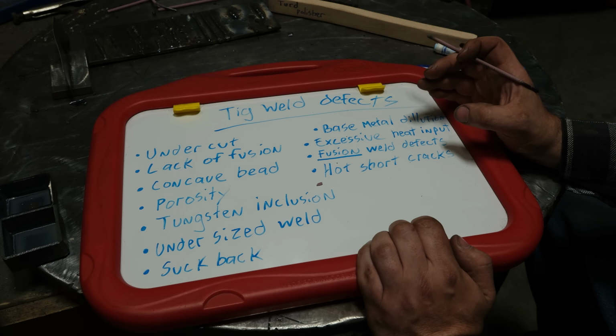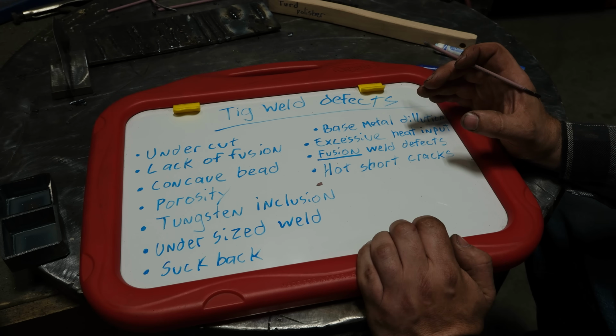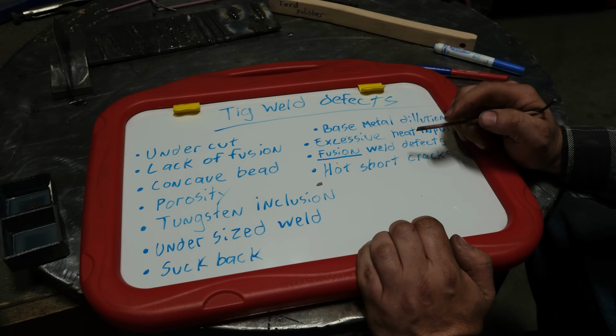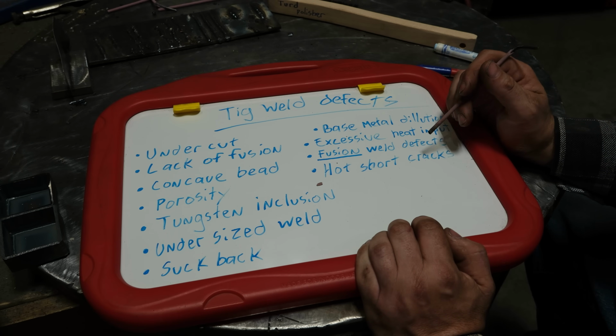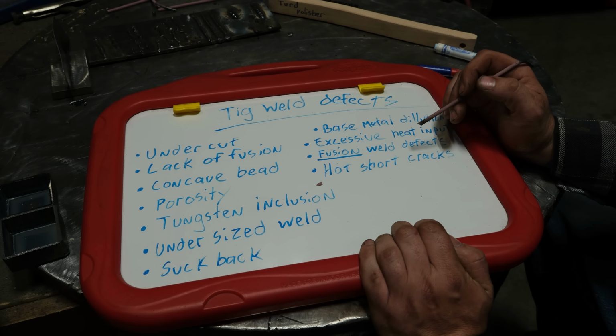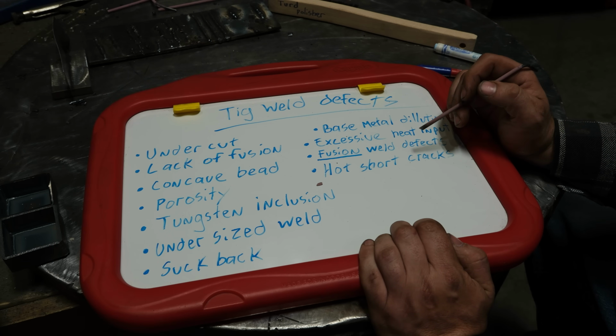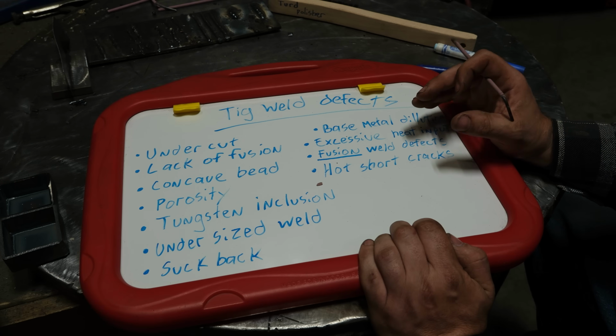And where you have cracks, guess what? Propagation of those cracks is very easy. So with hot short sensitive materials, you want to be very careful on how fast you bring the material to being molten, how fast you weld them, and how fast you allow it to solidify.